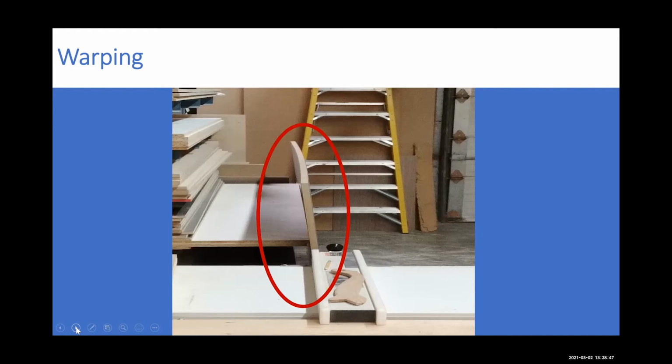If we look at warping, it's different from cupping. The deformity occurs when the moisture content of different parts of a piece of wood changes unevenly. So, for example, the mill worker acclimatizes the laminate, but he stores his substrate in a lean-to outside, and it's minus 40, and he brought that in and didn't acclimatize the substrate.